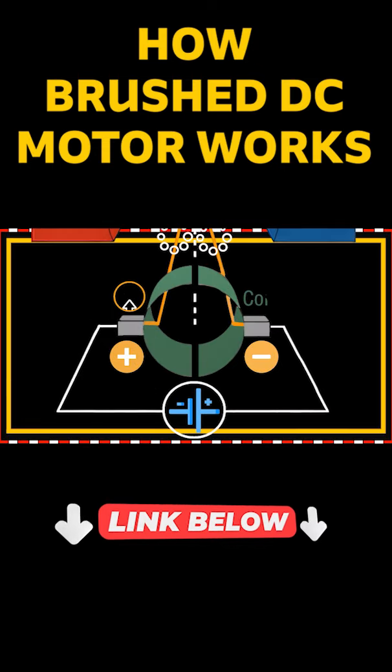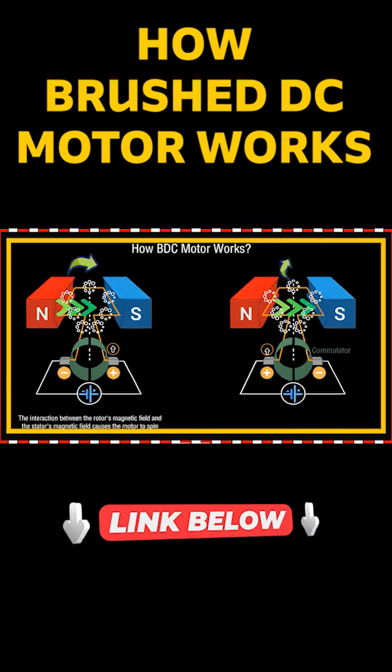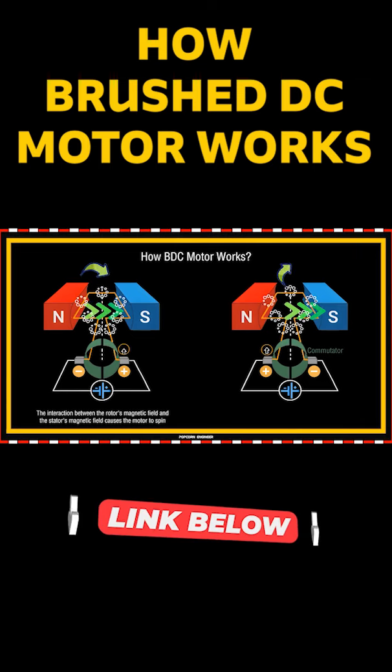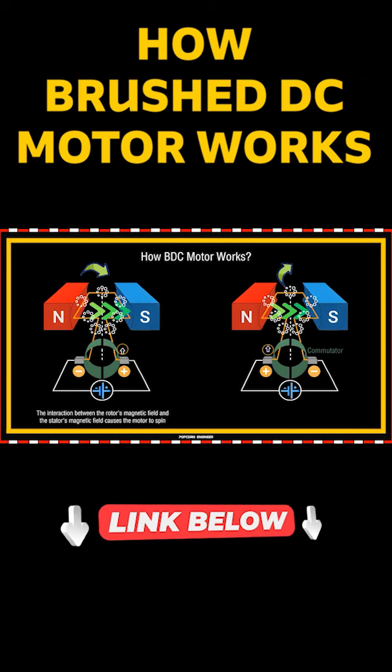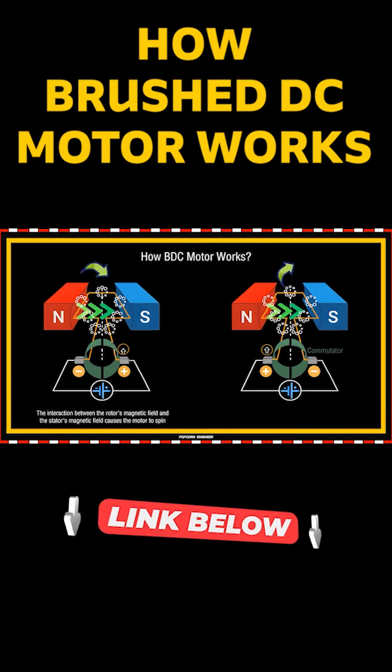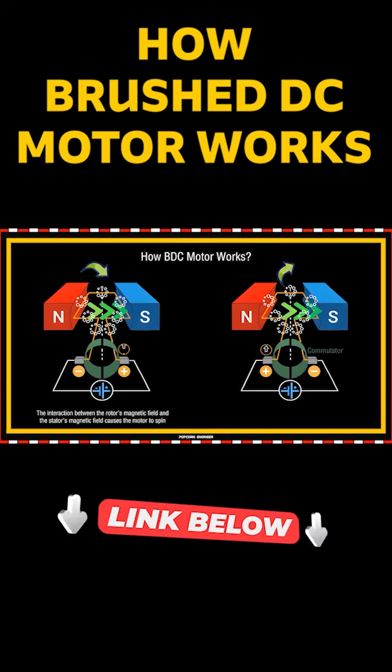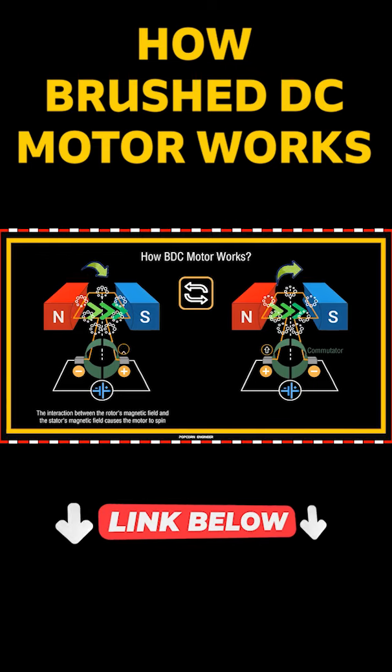That's where the commutator comes in. As the commutator rotates, it reverses the polarity of the current in the coil, causing a change in the direction of its magnetic field. As a result, the coil rotates to align with its new orientation. This explains why brushed motors need brushes: to maintain electrical contact with the commutator in order to reverse the polarity of the magnetic field each time the motor rotates 180 degrees, resulting in smooth and continuous rotation.